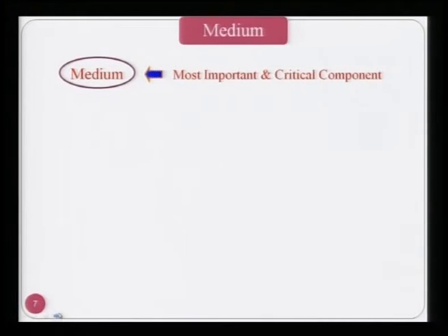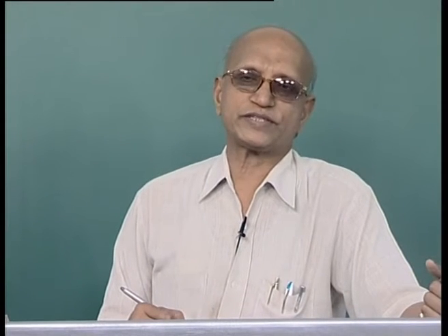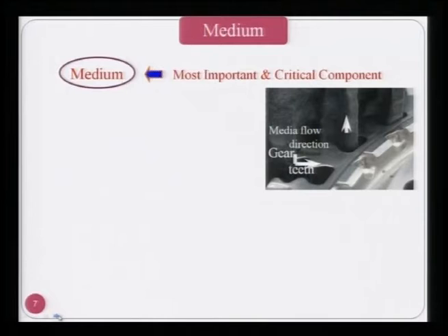The medium is the most important element of the whole setup because it is responsible for finishing the component. Now please see it very carefully. Here is a gear and this is the medium, coming down and going up, and it is coming in contact with the area to be finished. All teeth of this particular gear can be finished in one go. You need not finish individual teeth separately, which normally you do when you are finishing mechanically by hand or otherwise.